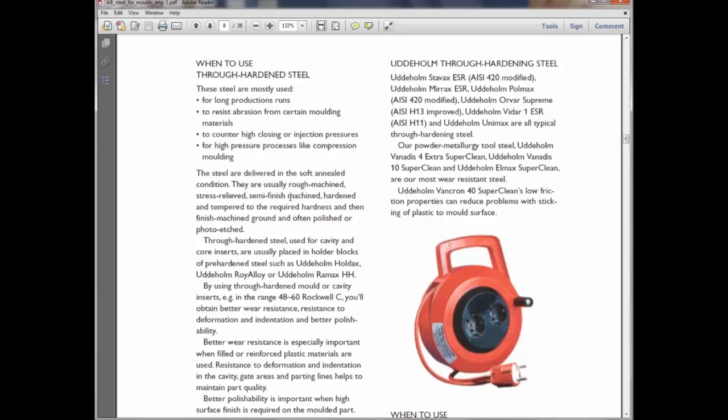So we counter that and remove the deflection with the help of machining. We always use many gauges which tell us how much is the deflection, how much is the bend, and then we remove that bend with the help of grinding, not with direct machining, because the bend is hardly 0.1 to 0.2 mm.